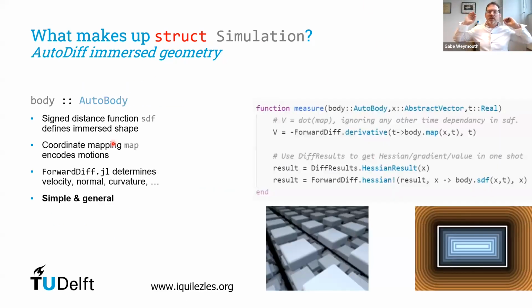Cool. Last thing I wanted to talk about, well, I guess two more things, is the geometry. I maybe didn't say it long enough, but the nice thing about the BDIM approach is that the momentum equation is still a very simple algebra update, just adding some coefficients. There's no real additional difficulty in the momentum equation itself. The only thing is that you do need to get the body velocity. You need to know where you are relative to the body so that you can get the kernel moments and things like that.